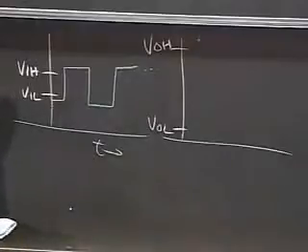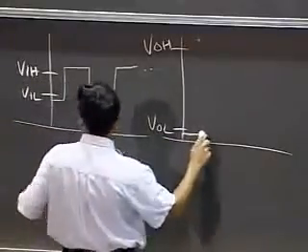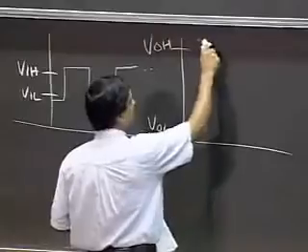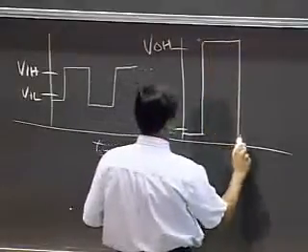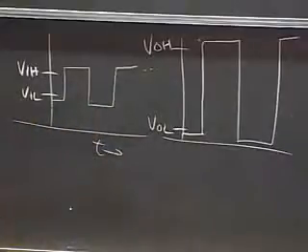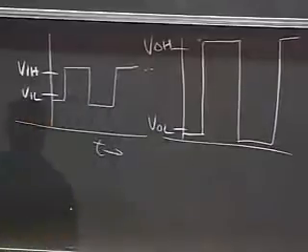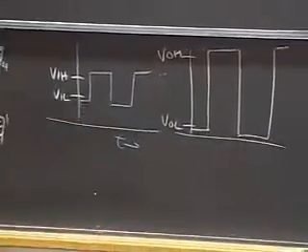So at the output, I'm required to stretch the 1s and 0s to be further apart from each other so that I get some noise margin. And the corresponding signal for our little circuit would look like so. Right? If this is a valid input, then this would be the corresponding valid output. Okay? Need I say more?